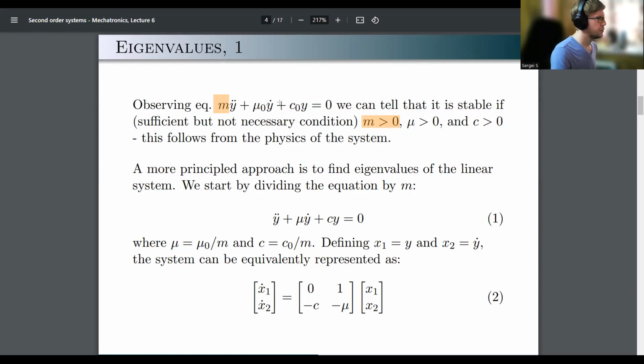So the first condition here is always satisfied. If you massage your equation into the correct form, the first coefficient is always satisfied. So it's not really a condition that you need to check as much as it is a condition that you need to acquire before checking. Okay. And then after you acquire this condition, first coefficient is positive, those two become necessary and sufficient conditions.